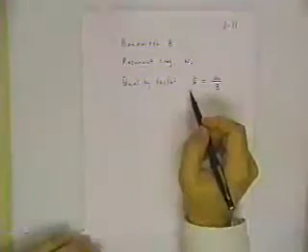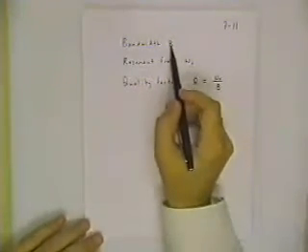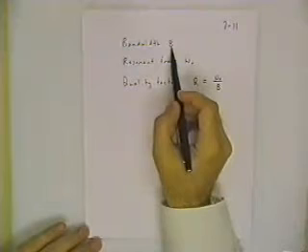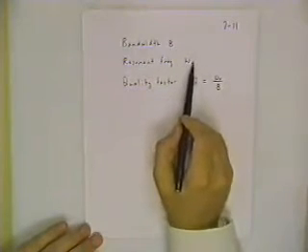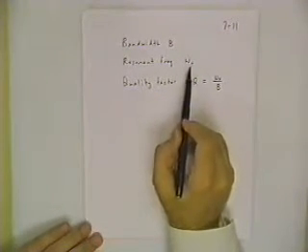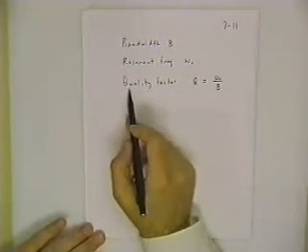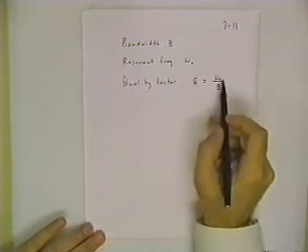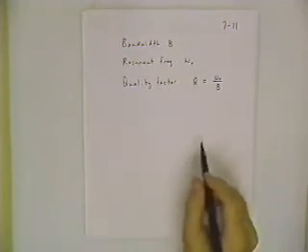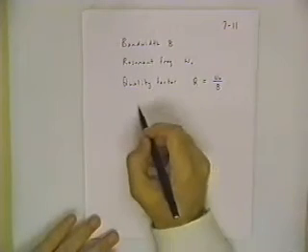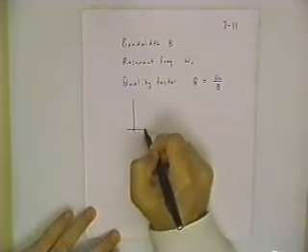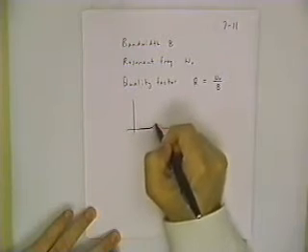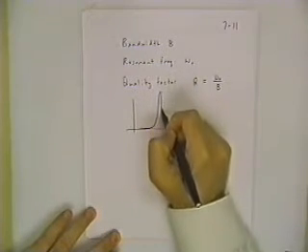So as I said, we have this resonant curve, and there's a band in the middle where it's got a very large output versus input ratio. So that range of frequencies is defined as the bandwidth. You have your fixed frequency, omega naught, the resonant frequency, and then there's a measure of the quality of your resonant filter, that's quality factor, the ratio of the resonant frequency to the bandwidth. Now you think of this as if the bandwidth goes down, the quality of the filter goes up. So here would be a very narrow band filter.